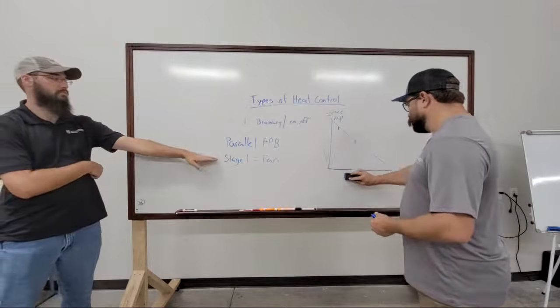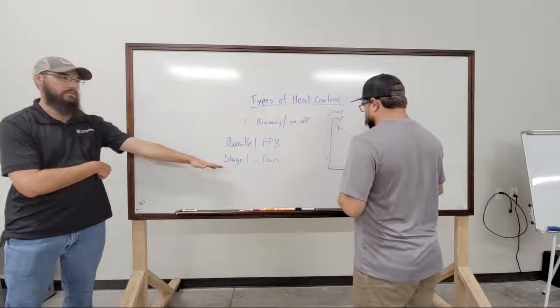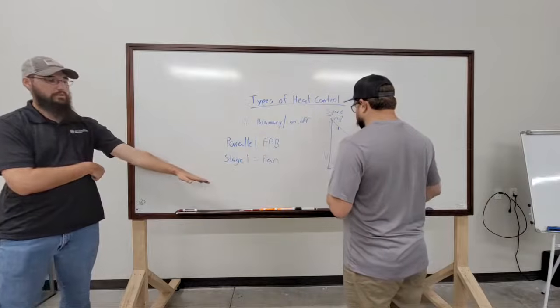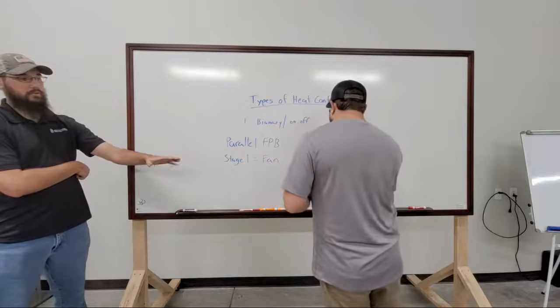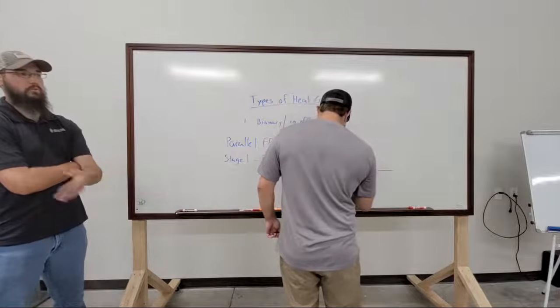So first stage typically is going to be fan. Second stage would be, say, your first stage of actual heat. Third stage would be a second set of heat strips coming on, and so forth as it continues.